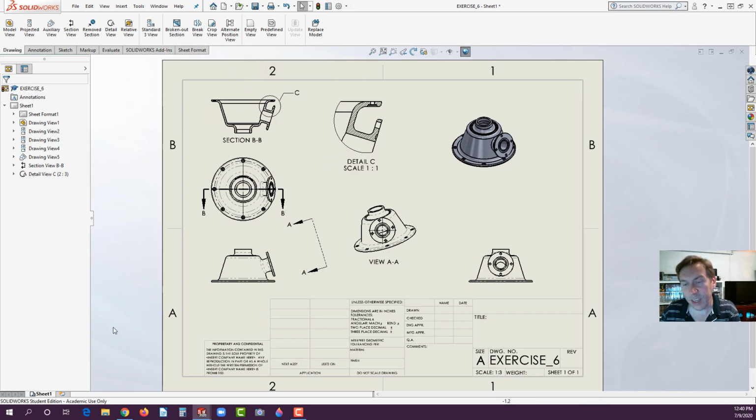All right, now we're going to take a look at another option here. SolidWorks divides this drawing into two, you might say, layers, though I don't like to use the word layers because layers refer to something in other CAD systems for putting multiple variations on the same sheet. Imagine a sheet of imaginary glass sitting over the drawing template. See, right now, like this A or this 2 or the border, maybe I want to change the color of the border or add additional information in the title block or break it out a little bit more.